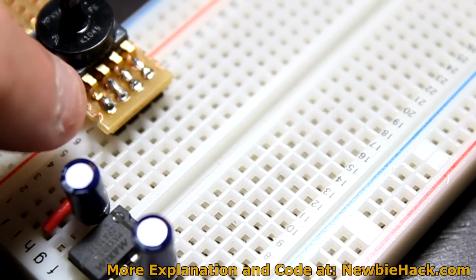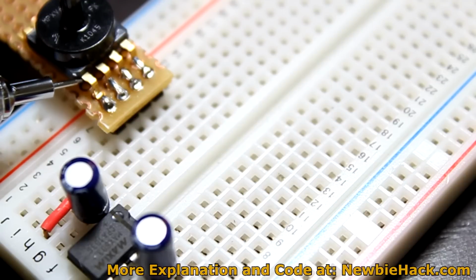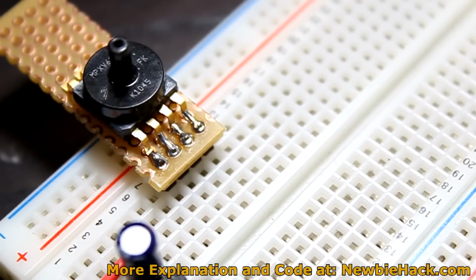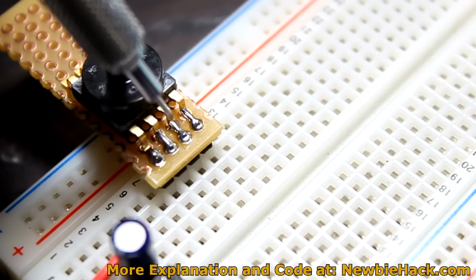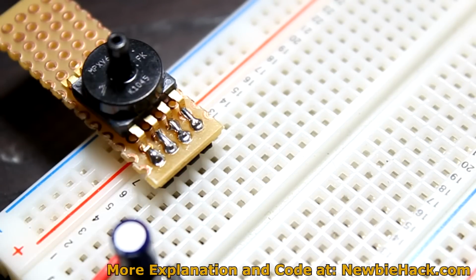We won't be using pin 1, which is located right here, and it's also the location where there's a slight angled portion on the sensor housing. Pin number 2 is the supply voltage, this VS. Pin 3 is ground. And pin 4 is the output voltage.